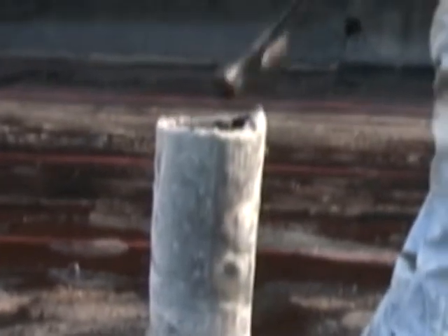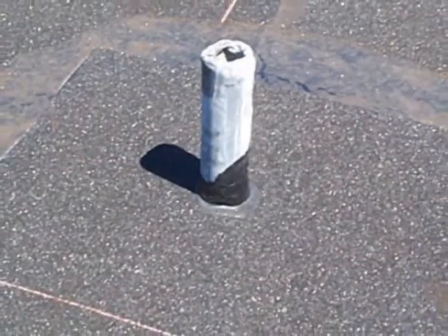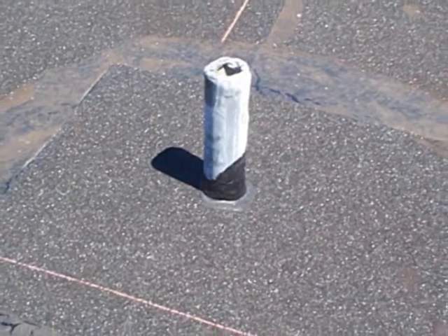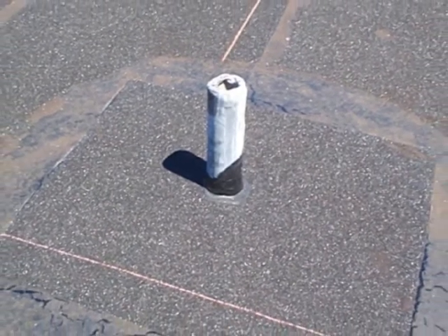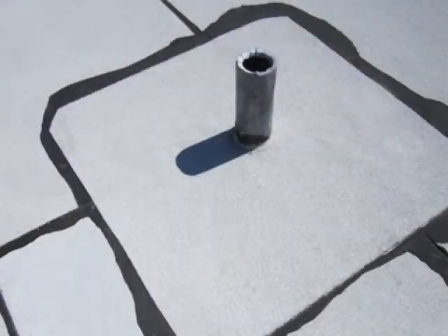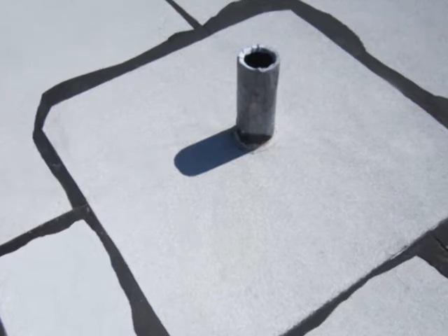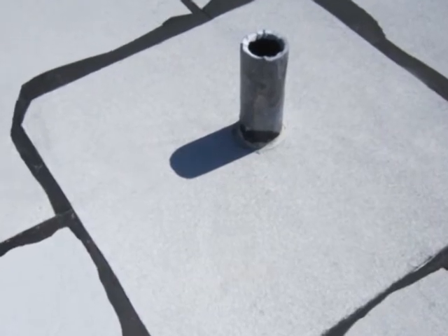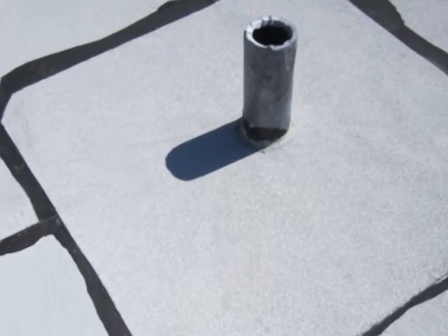Turn sleeve a minimum of 1 inch down inside the stack. Install base flashing plies in bitumen a minimum of 8 inches on the field of the roofing system. Install membranes in bitumen a minimum of 12 inches on the field of the roofing system. Caulk the intersection of the membrane and the vertical surface of the plumbing stack with polyurethane sealant.